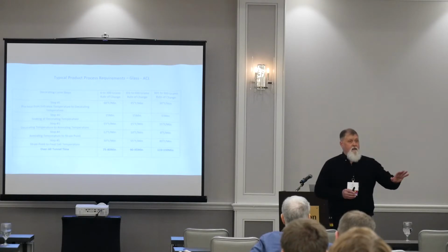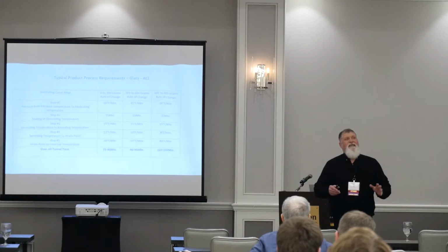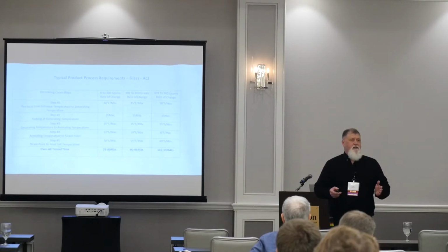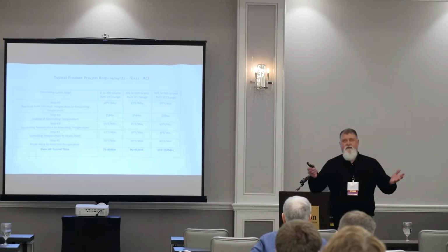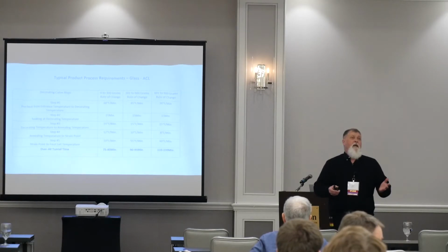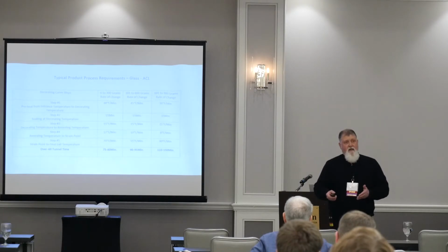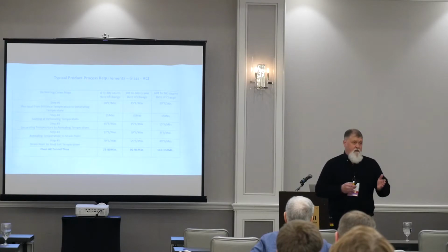Now, with an electrically heated leer, that's a whole different ballgame. It's very difficult to get excess heating capacity with any electric leer because you just don't have enough room to get enough element in there to pass the air by to get a higher BTU value. Most of the decorating leers, if they're Bowman's or really with anybody, you've probably got close to 1 million BTU per zone available to you with a gas-fired leer. With a decorating leer, it's going to be much less.